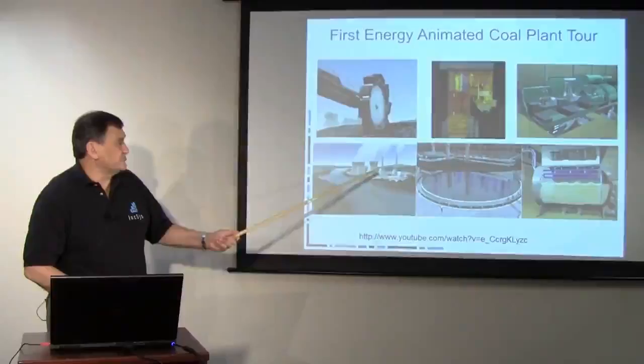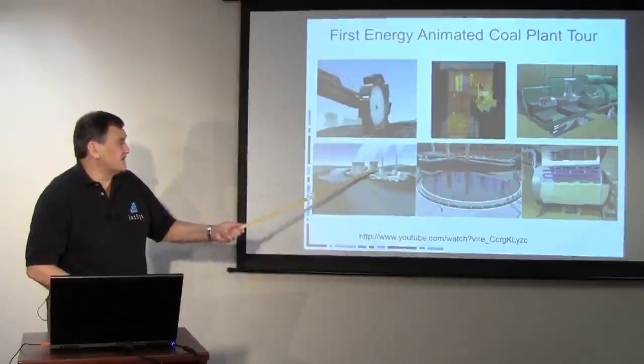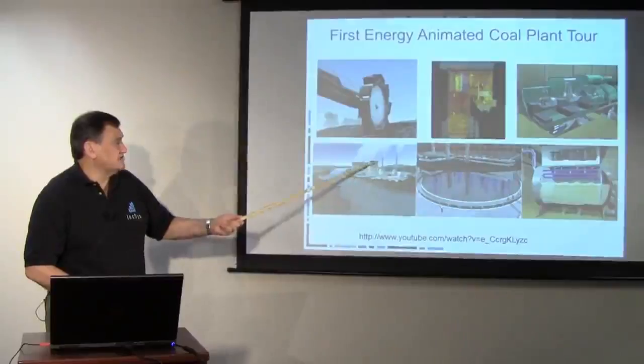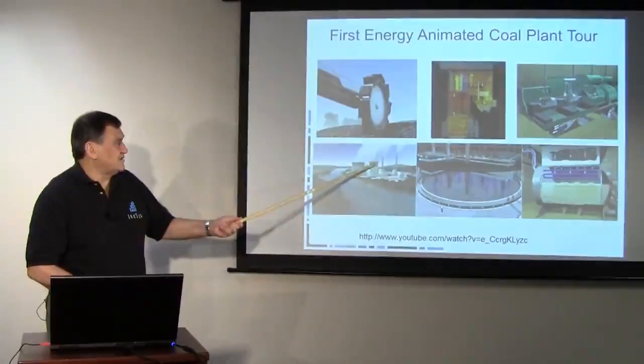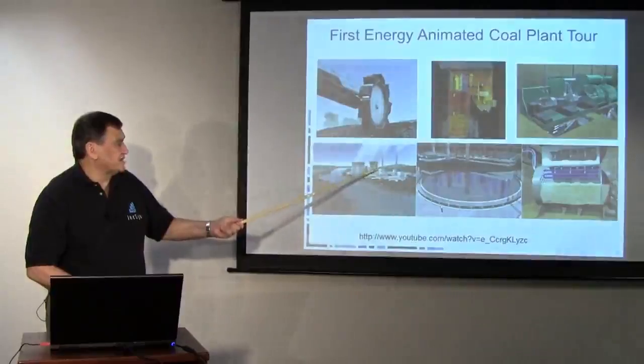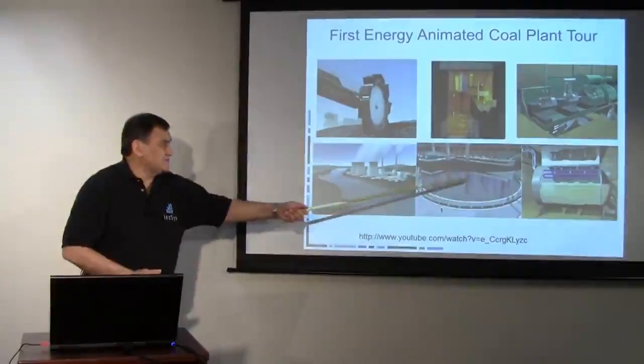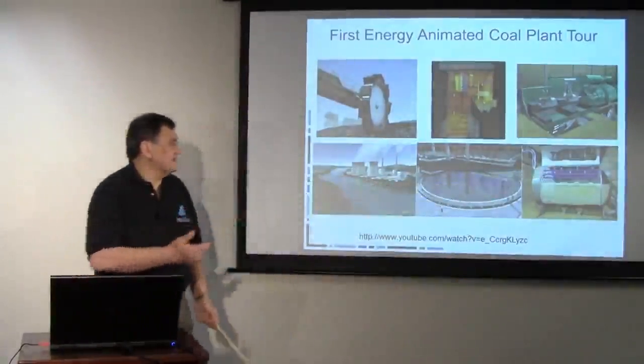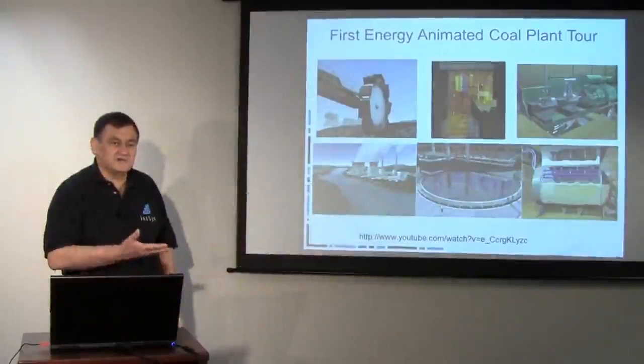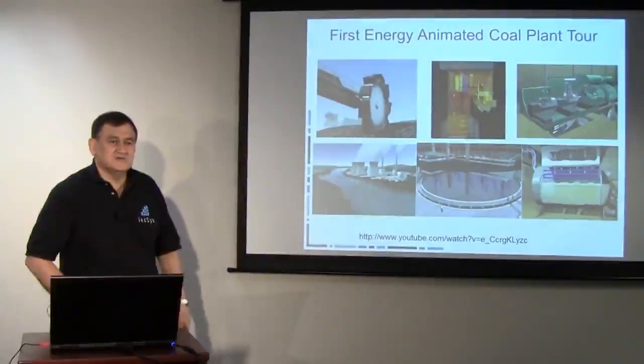And then this is the characteristic of the closed wet cycle. You see these huge cooling towers, and you see the effect of the air being brought in at the bottom, and then it comes on up, and through the latent heat of vaporization, typically about 1% of this water evaporates, and that has a cooling effect in that the water coming into the tower is hotter than the water exiting the tower. The water exiting the tower is typically about 10 degrees less than the water entering the tower.